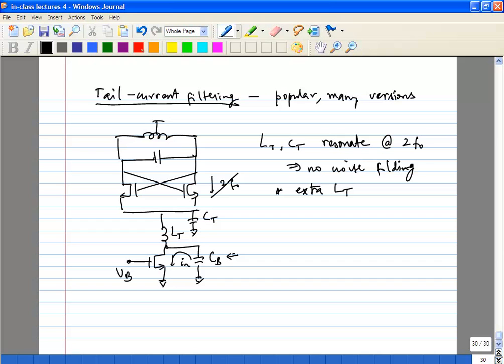Okay, and you will see it when you design your VCO. You need to make sure that you choose a large enough number of harmonics, and same thing with the mixer, by the way. When you do the steady state analysis, you will need to choose a number of harmonics that the simulator is going to consider for the circuit. So if you keep increasing the harmonic number, what you will see is the noise will keep increasing little by little. Eventually it will settle down to some value, and that is the number you should be using for all future simulations. Same thing for the VCO.